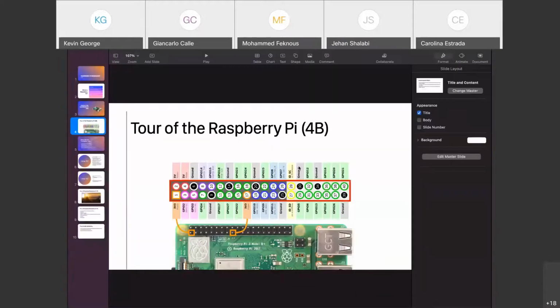When you're setting this up at home using the kit you received, you're not going to have a male header. On yours, you would need to solder that on. However, what I'm doing with my kit is placing the Raspberry Pi onto the breadboard and then punching through the wiring so that they are going through the Raspberry Pi onto the breadboard, making that connection.